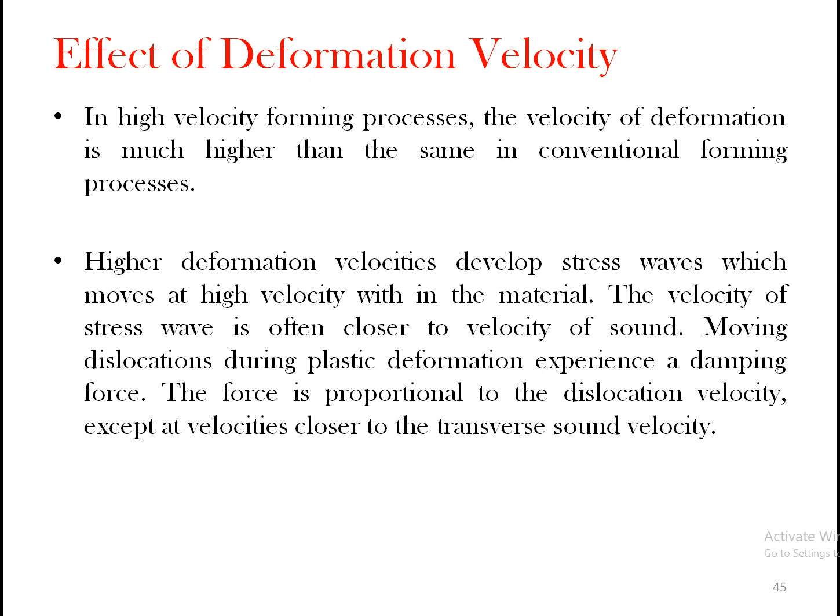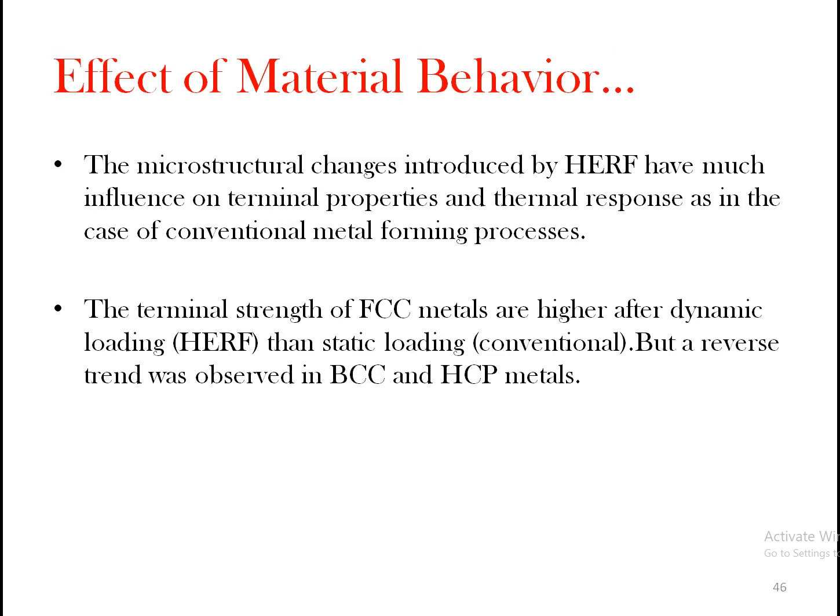Moving dislocations during plastic deformation experience a damping force. The force is proportional to the dislocation velocity, except at velocities closer to the transverse sound waves. So when the velocity developed is almost closer to the velocity of sound, because of this, the material deforms plastically. Now the effect of material behavior: the microstructural changes introduced in high velocity forming have much influence on terminal properties and the thermal response, as in the case of conventional metal forming processes.